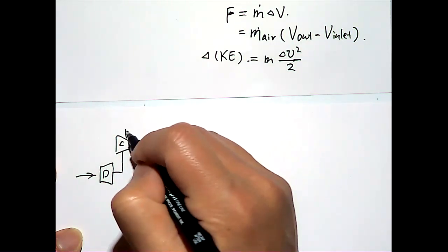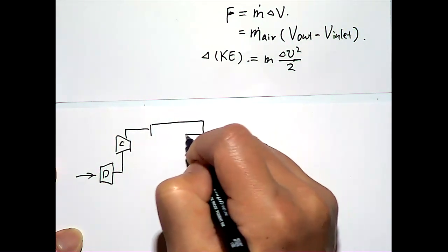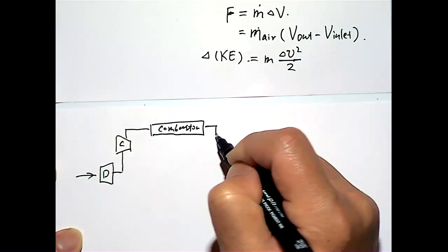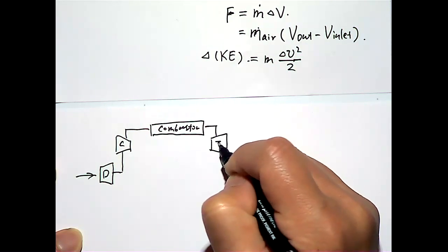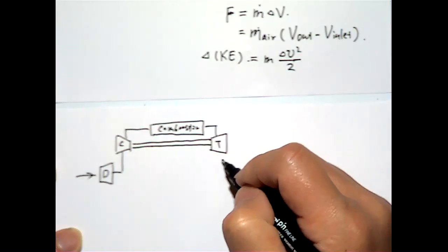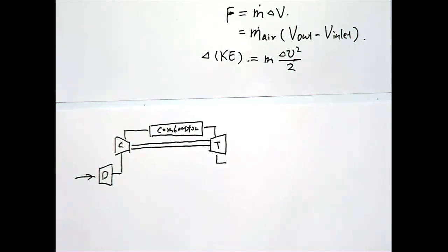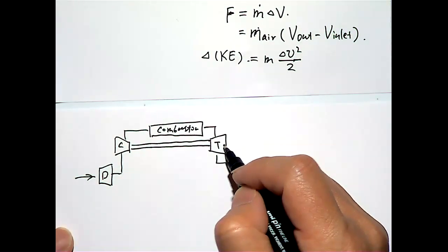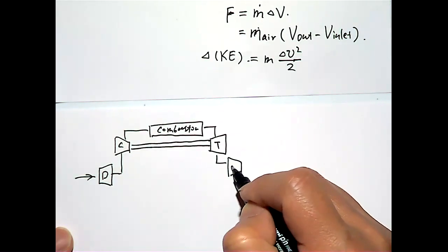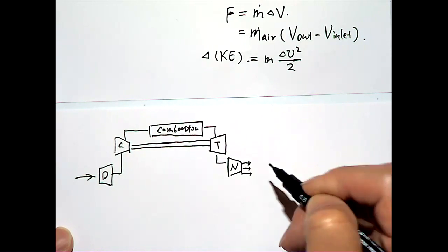The compressor then goes into a combustor, which drives a turbine. The function of the turbine is basically to drive the compressor, essentially. This turbine does not output useful work. So the unused thermal energy from this process then goes through a nozzle to produce the thrust.